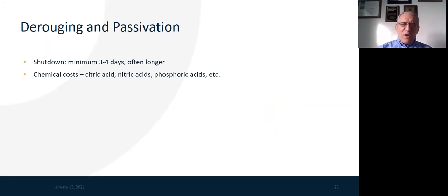Don't forget, purified water systems that are using heat sanitization are often run at elevated heat temperatures. So mainly you're looking at derouging passivation of both your PW systems and your WFI water systems over time.